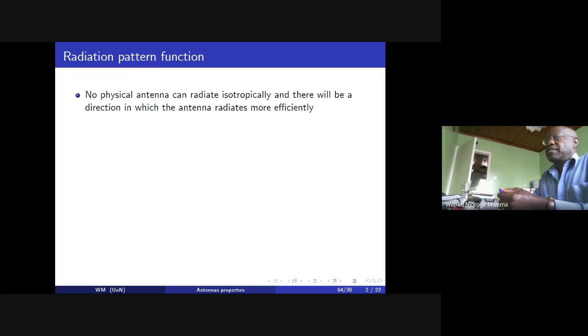When we saw that for the Hertzian dipole or the magnetic dipole, it had a perfect kind of radiation pattern, in which the electric field is radiated as a figure 8 or a donut kind of shape, while on the horizontal plane, of course, it's circular, and in the vertical plane for a vertically oriented dipole, we saw that it was a figure 8.